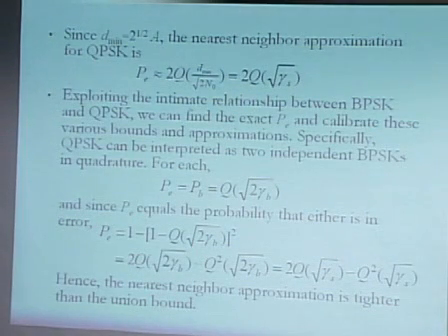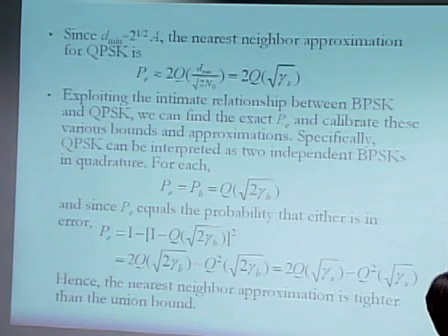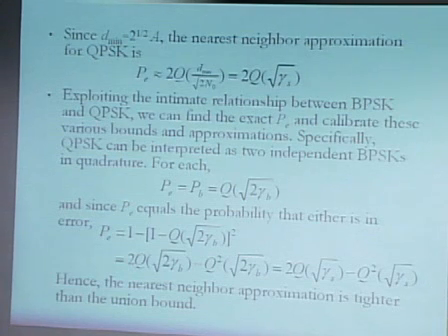Yes? So you're saying that they're independent, the two, but they're really not. Because the nearest neighbor is telling us that if there's an error, it's going to go to the nearest neighbor. It's not going to go up from negative A to jA. It's going to go to probably negative A or A, right? Right, so you're saying, okay, this point over here, for example, will probably end up being mapped to the other BPSK.